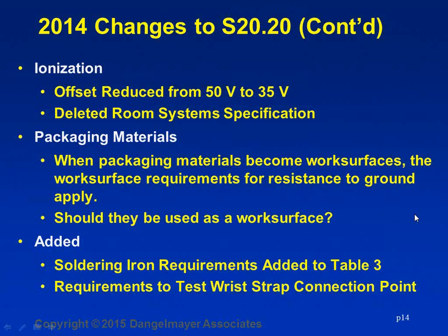Obviously, you can't rip up your floor and put it in a 12% humidity chamber like the qualification test requires you to do. But if you could do a consistent body voltage test on the different paths where you walk on that floor throughout the year, it'll give you a good picture of what it's like and what it's doing for you.